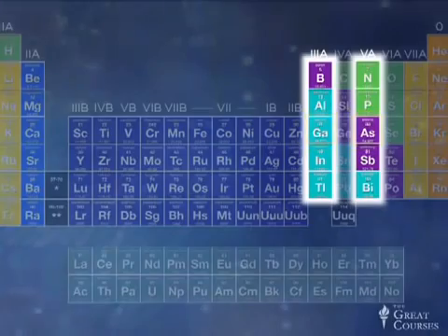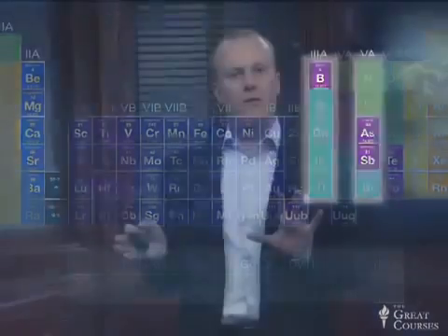So thinking back to our periodic table, we've achieved a good match. Group 3 and group 5, they together will satisfy a full electronic orbital, the way silicon, 4 plus 4, will satisfy a full electronic orbital. They also rely on covalent bonding, so they're very, very strong. They're very robust materials. But by introducing another element, by having a pair of elements, or in fact, we can introduce a third or a fourth element from group 3 or from group 5, we have more degrees of freedom.